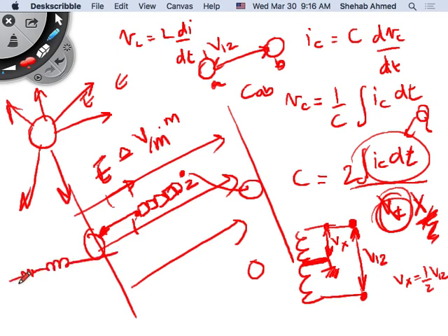Remember, my equivalent circuit is this. This is my short line equivalent circuit for the transmission line. I'm trying to calculate the capacitance between the tower and ground. So I will first calculate the capacitance between 2 points in space, or two conductors, and then multiply that by 2 to calculate the capacitance between tower and ground. Then divide it by 2 again, because this is jB over 2. They put half the susceptance here, half the susceptance here, right? So that's where this is all going.